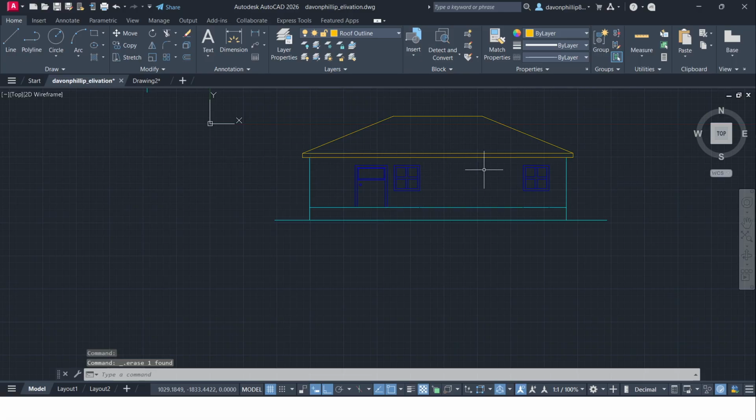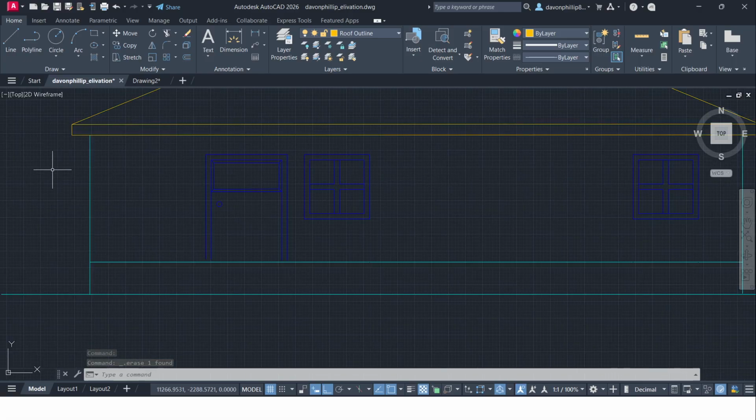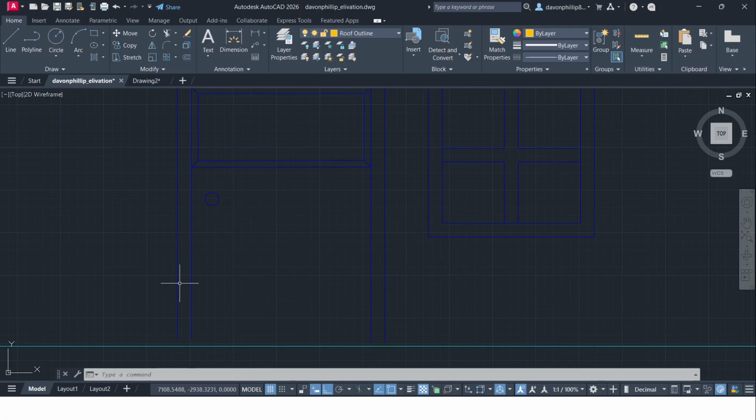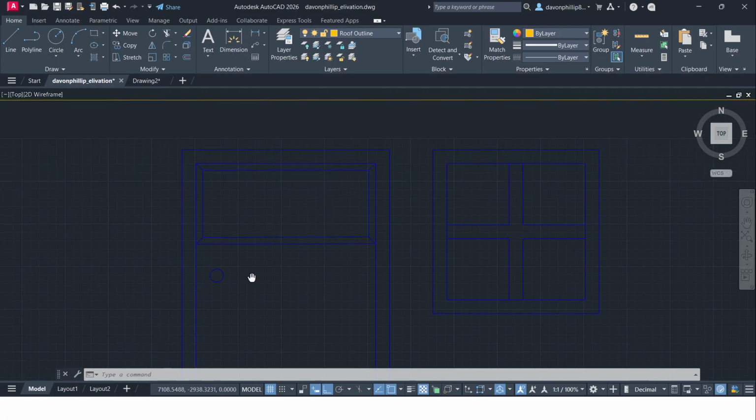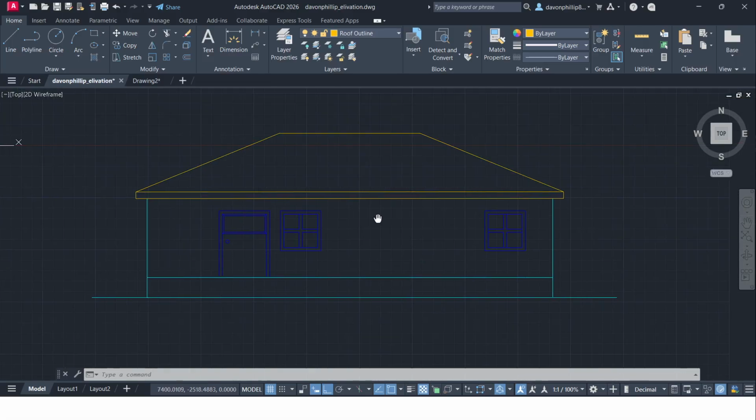But the windows and things, that's easy. If you don't get the Design Center to work, just make the door design for yourself. How I do this, I offset the frame by 100, offset from the actual door by 100. This is just a circle. I offset again by 50, I think, right? So this rectangle inside here is offset by 50. And I just put diagonals in the corners to make it look like the door design.